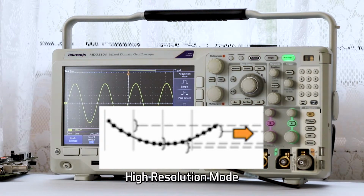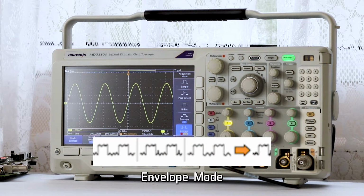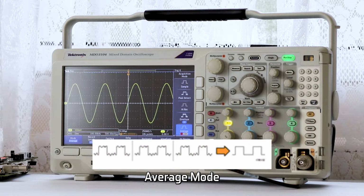High-resolution mode calculates the average of all samples for each acquisition interval. This mode also works only with real-time, non-interpolated sampling. It provides higher resolution at the expense of lower bandwidth. Envelope mode finds the highest and lowest record points over all acquisitions. Envelope mode uses Peak Detect for each individual acquisition. Average mode calculates the average value for each record point over a user-specified number of acquisitions. Average uses sample mode for each individual acquisition.